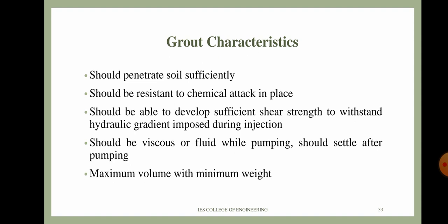Moving on with grout characteristics. The grout characteristic has an important role in grouting. In order to obtain the desired effects, a grout should have certain characteristics. That is, it should penetrate soil sufficiently, and it should be resistant to chemical attack when in place, and the grout should be able to develop sufficient shear strength to withstand the hydraulic gradient imposed during injection and on flowing groundwater. It should be fluid while pumping and should settle after the pumping also. Maximum volume with minimum weight is the effective character of grout.